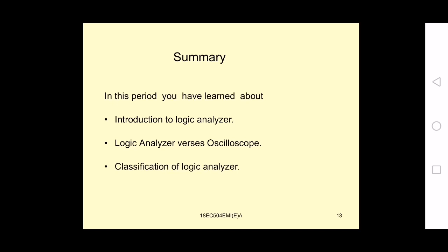So both are useful in troubleshooting. One is in the analog domain, and the other is in the digital domain. And the classification of logic analyzers: logic state analyzers and logic timing analyzers. The logic timing analyzers are asynchronous and the logic state analyzers are synchronous.